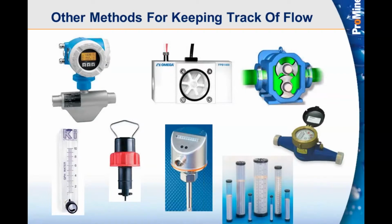Top middle is just a little paddle wheel flow sensor. It's very appropriate for us for some applications. That's typically for an instantaneous flow rate. We need another device to connect that to really be able to totalize it or even display that instantaneous flow. What we use now on some of the pumps is kind of that top right display. We use another manufacturer for that, and we get a totalized flow into some of our boiler and cooling tower controls. So we could potentially replace that with the Dulcoflow in the future. That also gives us a nice local display where we don't have that on that current device we're using.